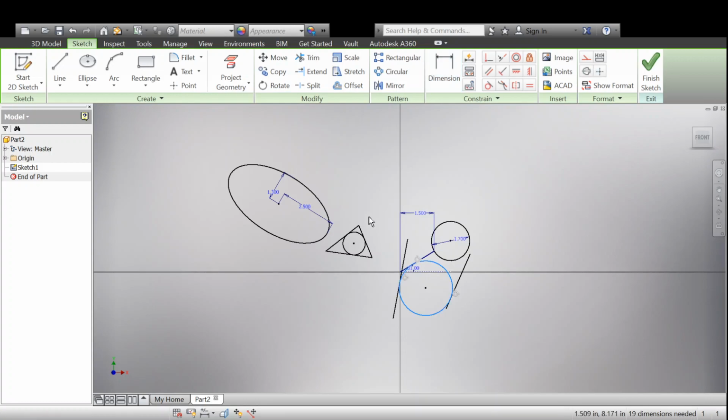But it's important to recognize that, look, if there's already a number, you don't use the dimension tool. Just double-click the number. So try it yourself, please. On your ellipse you just created, double-click one of your dimensions. It should allow you to alter that dimension now. So try to double-click on any of your dimensions.